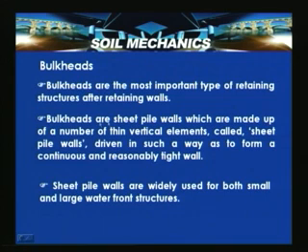So bulkheads are sheet pile walls which are made up of a number of thin vertical elements called sheet piles, driven in such a way as to form a continuous or reasonably tight wall. And sheet pile walls are widely used for both small and large waterfront structures. These are also used in some cases as part of berthing structures in the marine environment also.